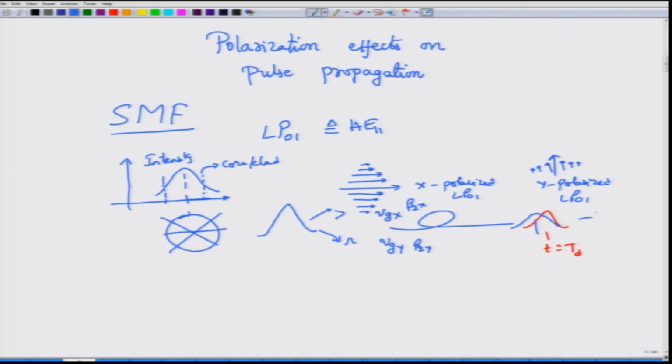But now when you put it through a detector, you want to detect what would be the output, since the detector is only going to look at E cross H, or E cross H conjugate, which if you remember is actually the Poynting vector, correct. And since you are considering scalar variables and transverse coordinates, what this actually means is that you are looking for |Ex x hat plus Ey y hat| magnitude square, and the detector cannot detect the fields, it can only detect the power. What it actually detects is this combined pulse which would then be looking like this, right.